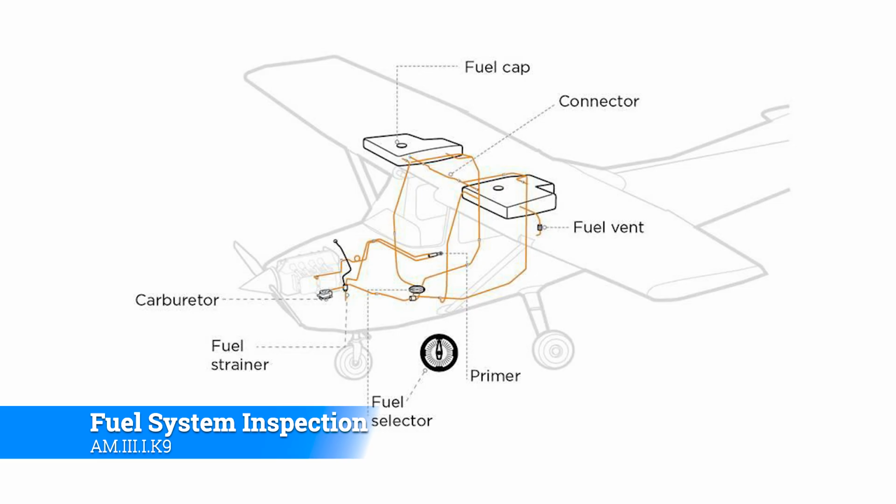This includes all of our filters and screens. We're looking for any kind of sediment, and any sort of slime is another thing that could potentially grow. A lot of these fuel additives will in turn allow for biological growth, so you're going to want to make sure that the fuel doesn't have some kind of weird slimy sludge growing, some sort of microbial life that's taken up residence inside of your fuel system.